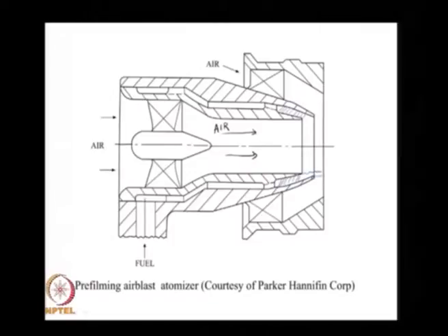So, you have a liquid film that is spilling over, that is impacted by the air on the inside and outside. This is our simplest air assist atomizer. Let us take a case where there is no air on the outside. So, just for the sake of our argument, we will keep it simple. We will look at air only on the inside, that is swirling, and we have a liquid film coming out.